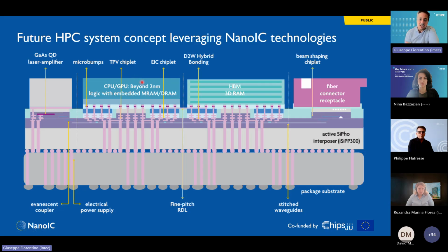Of course, how do we make sure that this logic unit is talking with the memories? Well, we have the memory chip sitting on the side, and there can be multiple memory chips sitting on the side, all connected through what we call an advanced interconnect system, which can be sitting over an interposer. In this case, it's an electro-optic interposer with silicon photonics, but it can also be just an electrical interposer, and it allows us to overcome several issues that we see already ahead of us.